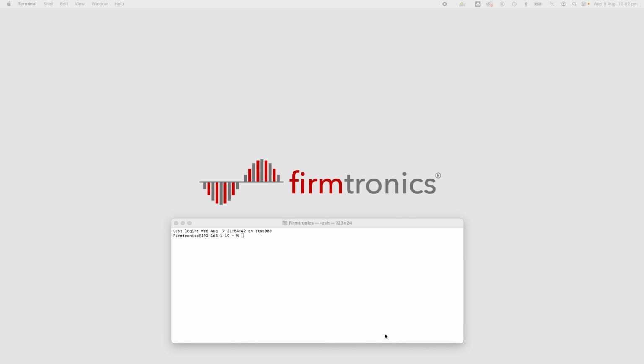So I'm going to install OpenOCD. OpenOCD stands for Open On-Chip Debugger, and basically it's an open source software tool used for debugging and programming microcontrollers. So the best way, in my opinion, to install OpenOCD is to use Homebrew that we installed earlier. So if you type in brew install openocd, it'll go ahead and install it.